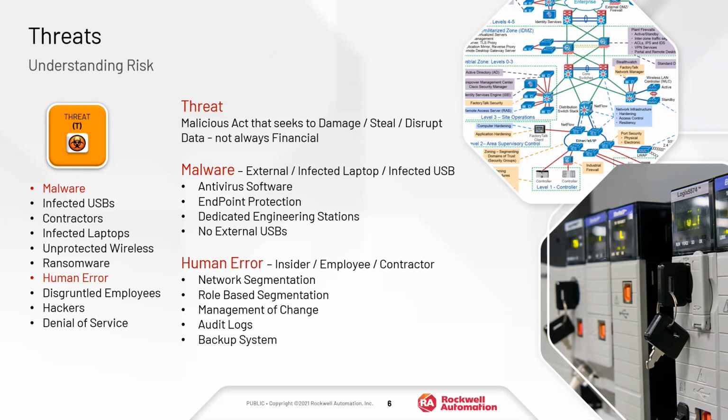So some of the countermeasures that we typically start looking at are protection of the industrial control infrastructure, so the network and the servers that are there. The first one is just installation of antivirus software. This is protection against known threats. There's a huge database. If we know that a malware exists, typically these antivirus software, especially if they're kept up to date, will be able to protect against that. They'll see the same signature that's assigned to that software and block it, keeping it from infecting or propagating through the system.